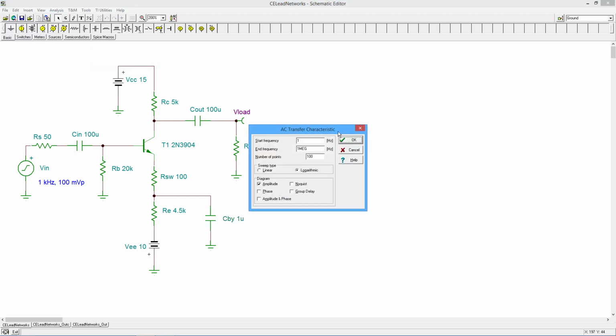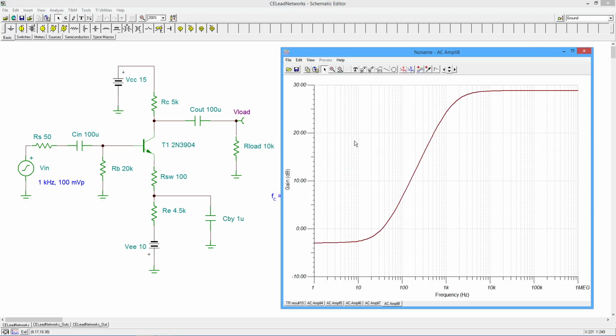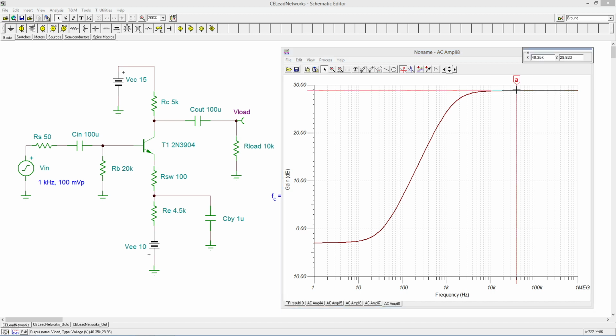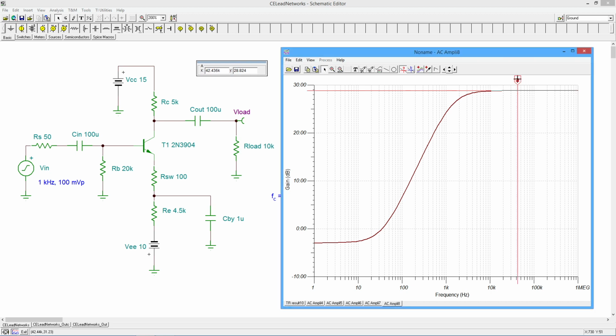In any case, let's go back to our analysis one more time. Alrighty. The usual. Hey, look! So here's our first break. It comes down like we saw before, and then it flattens out, unlike what we saw before. So let's get our cursor out here. Let's see what we got. So no big surprise. The flat part's 28.8 again. So where does this fall to 25.8? Somewhere around there. And that's 1.376K. So I approximated that as, like I said, 1400. So that's looking really good.